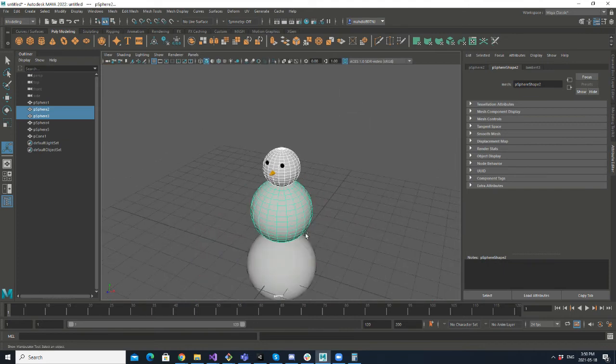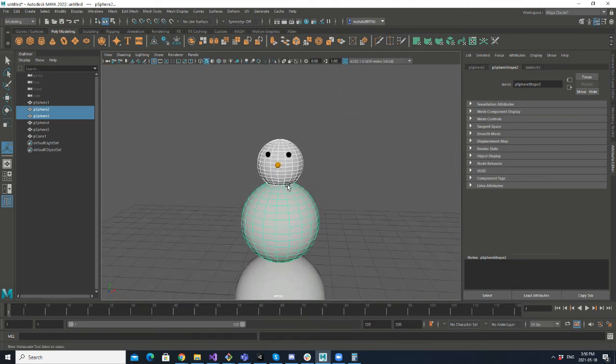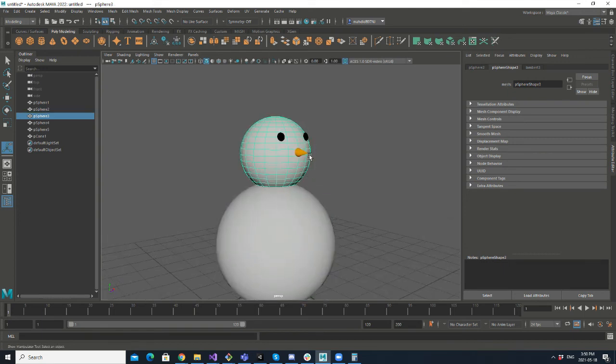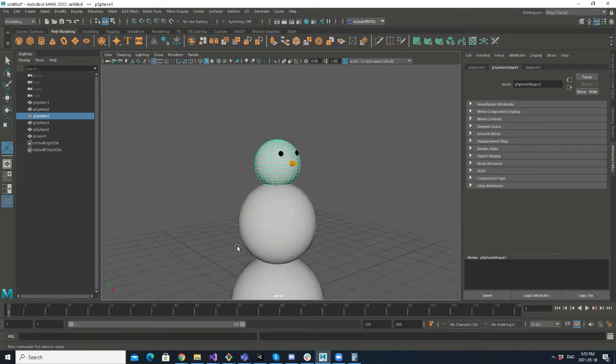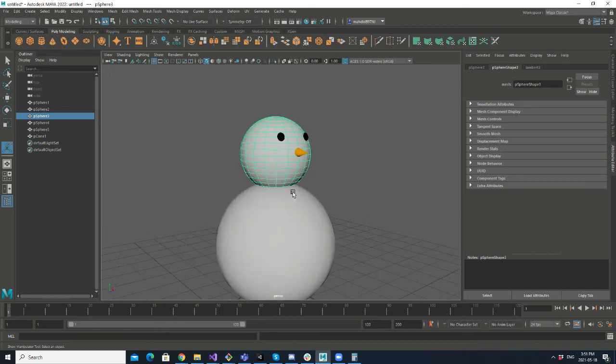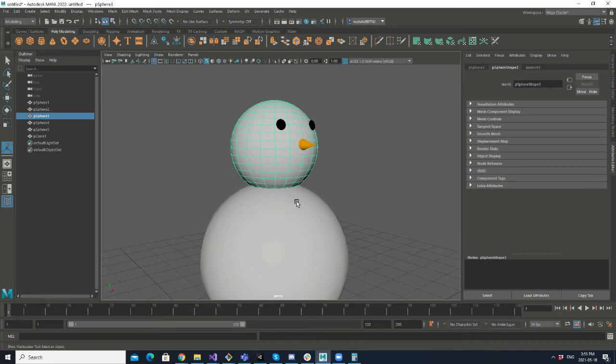What I'm saying is that these intersections between different objects, which is the same as, for example, the nose and the head, are kind of bad, because when you're animating your characters in future, you will see some bad shapes in the output from your character, because some vertices come out and some just get into your object, and that's not what you really want.